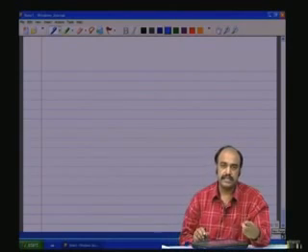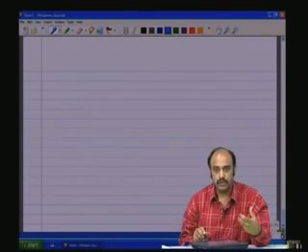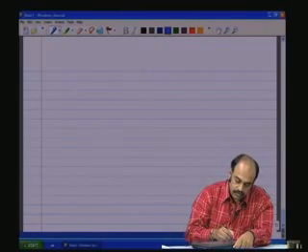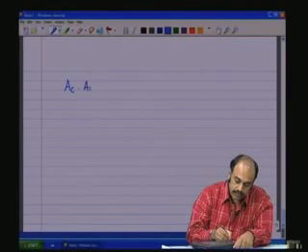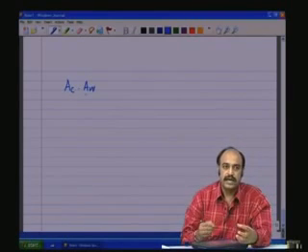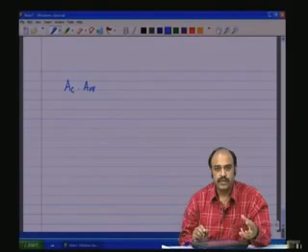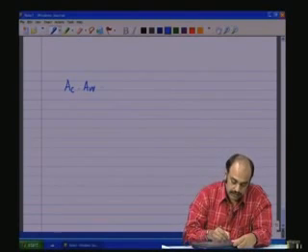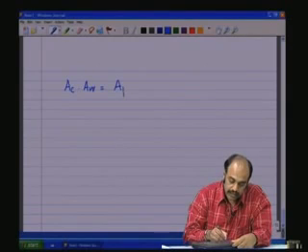The voltage capability is decided by AC or the cross sectional area of the core. Therefore, the product AC into AW should decide or should give an indication on the power handling capability of the core. This is the area product AP.